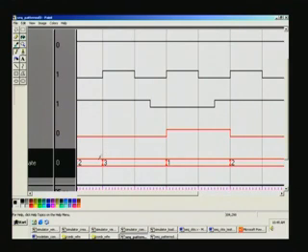So, the state itself is changing at this positive edge. Its corresponding output will get reflected only here, because it has to wait for entering the state only at the next positive edge. It has just entered the state, right. That state will be processed only at the next clock edge. Only after you process that particular state, you can get the output. That is why it is happening. Are we clear with this? No. So, I explained earlier.